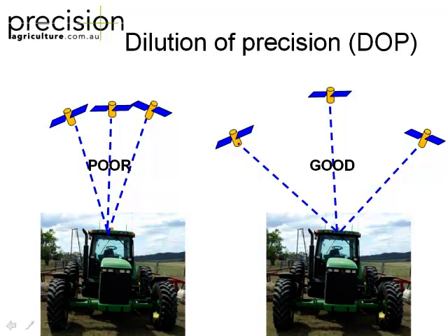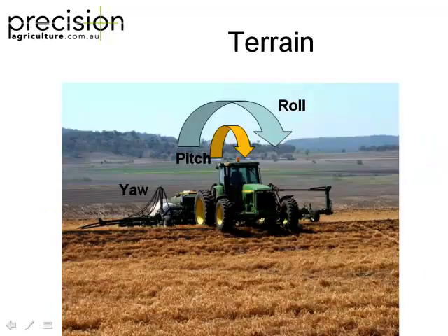DOP, I don't know if anyone's heard of DOP. You'll hear that if you do have a RTK system, obviously being high accuracy, they're going to be far less tolerant to anything going wrong, right? A handheld GPS is always going to get your satellite in a position, isn't it? Always. Well, a high accuracy RTK can often lose signal, and sometimes because the satellites aren't aligned properly. So you might have 6 satellites and it still tells you can't auto steer, but you have a look at your DOP values and they've gone through the roof. So it's all about how well the spread is in the sky. Does that make sense? For you to get good triangulation, good correction.